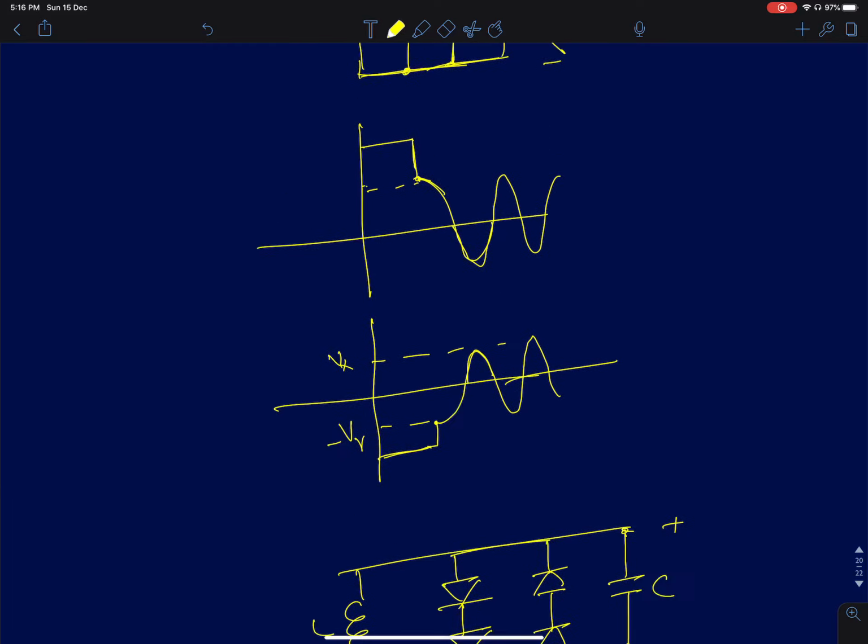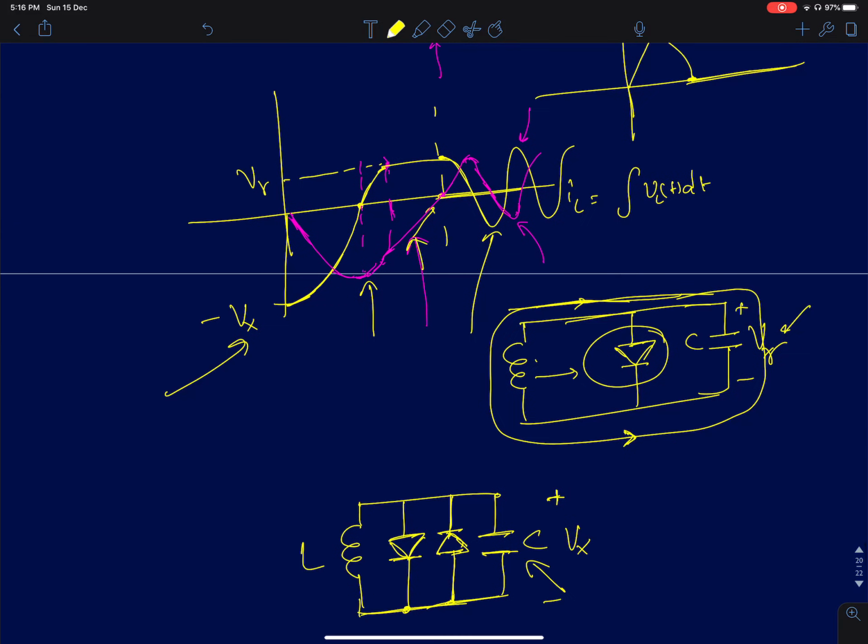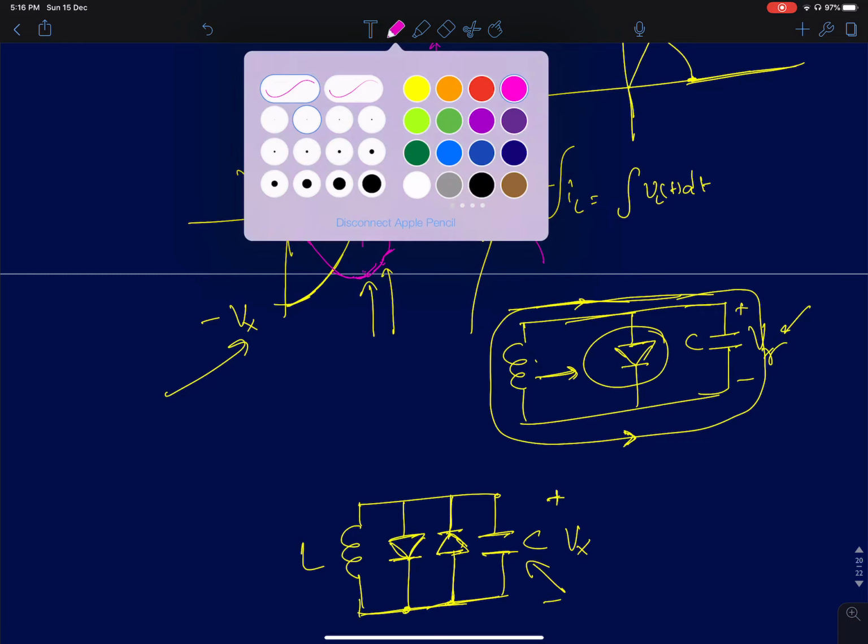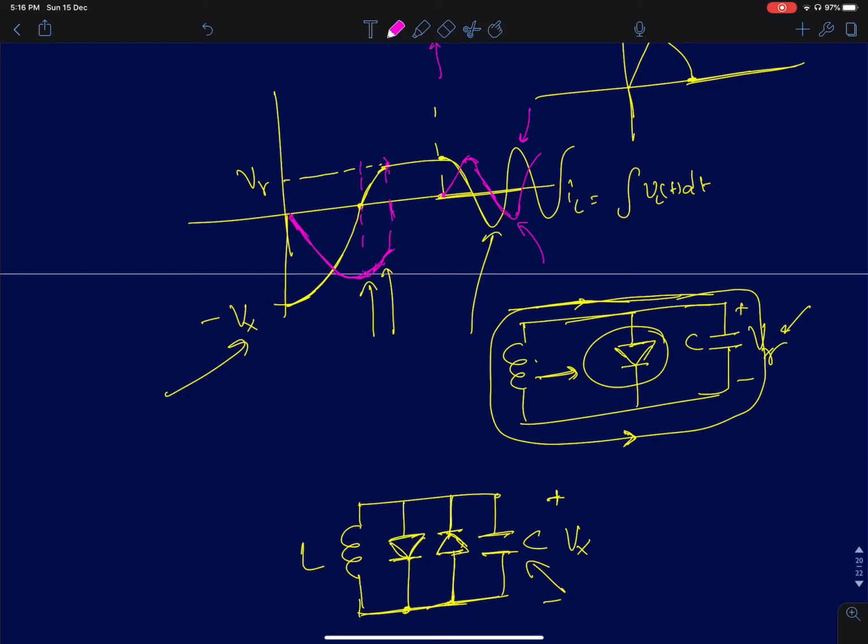In the previous problem, we discussed how the transition happens. I showed it in the time domain. The transition takes place in a nonlinear fashion. The inductor current will be initially sinusoidal, and the instant the diode starts conducting, we saw that the inductor current was reducing in a linear fashion. Probably I'll just redraw the inductor current. It was sinusoidal here. At this point, it then started to change linearly like this. After this point onwards, it's just going to behave like a standard LC circuit with an initial value of V gamma across it. So this is all about inductor circuits with diodes in them.